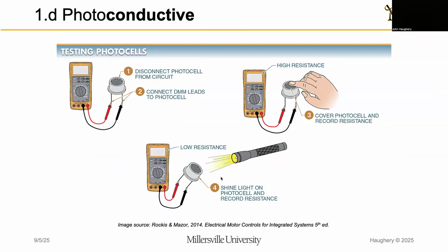The testing of all of these devices is similar, whether it's light or temperature or pressure. You would use a DMM on the resistance function, and you'd measure the resistance across that element, and you would apply full light or apply no light, and you're hoping to see a change in resistance, right? Or you apply full temperature or no temperature, depending on whatever physical phenomenon the sensor is looking to sense. That's what you're going to give in the extremes to see, do I see a change in resistance when I see an extreme change in light or temperature?